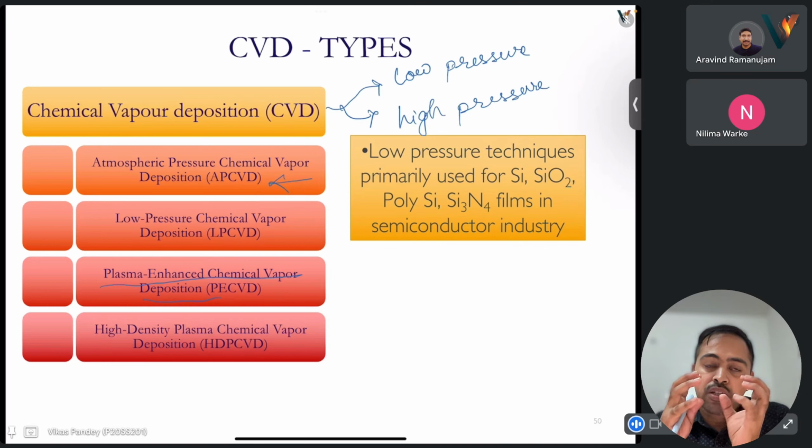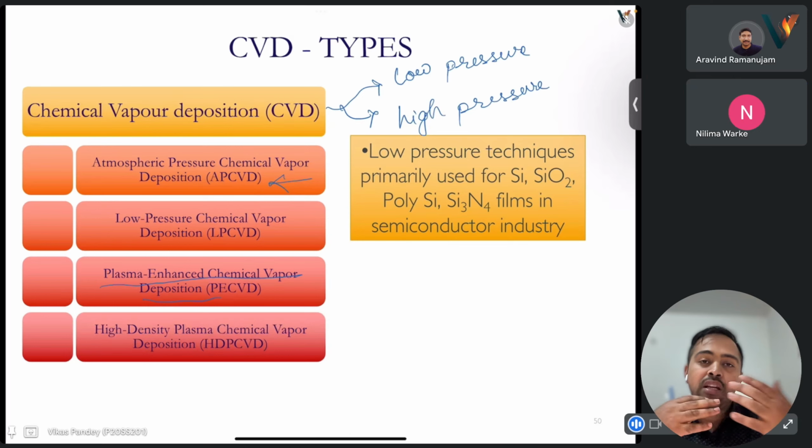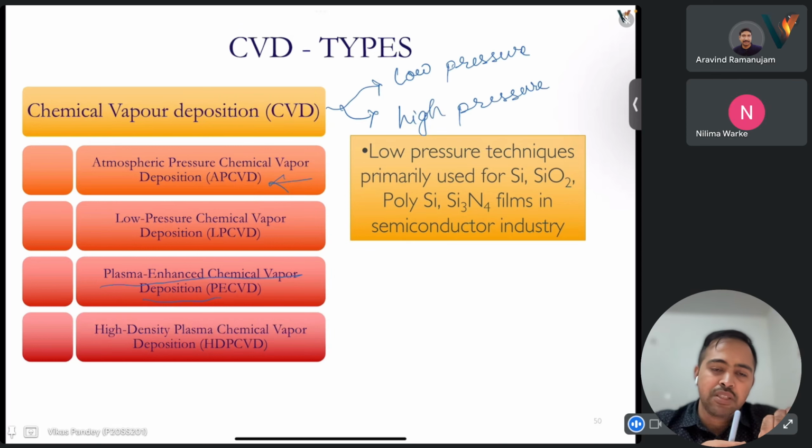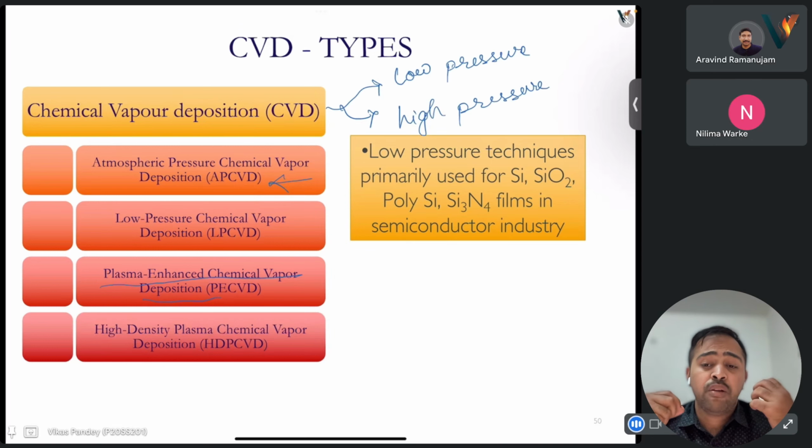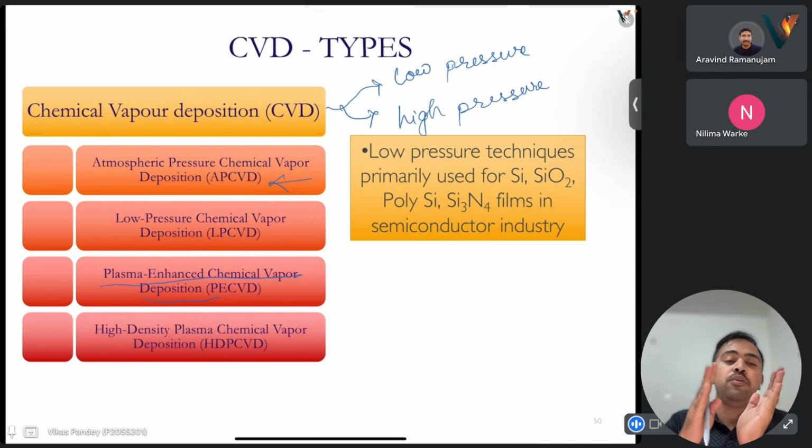It is somewhat like if you make a list. Suppose you are going to procure a CVD system, then you will make a list of what materials will I generally be growing. So if they are materials that can be simply grown using APCVD, that is the most cost effective one, the simpler one. But yes, it has limitations, like it will not give that good surface coverage. But it also depends on whether you are able to get what you want, like that will work fine for you.